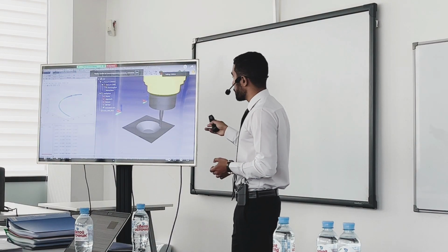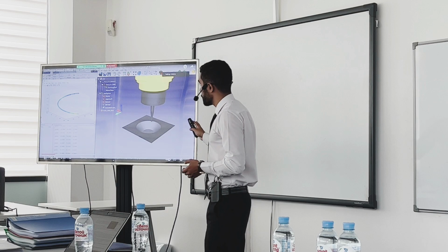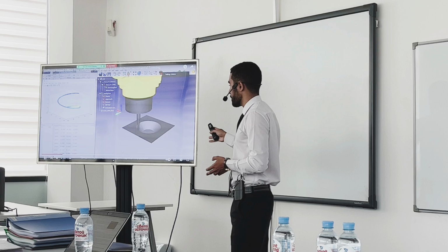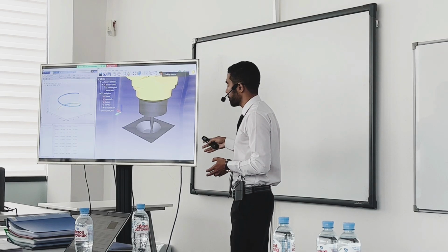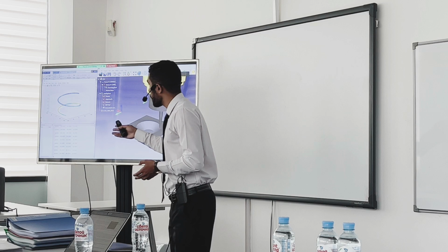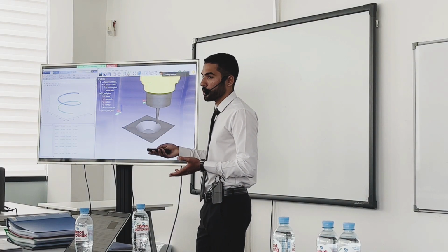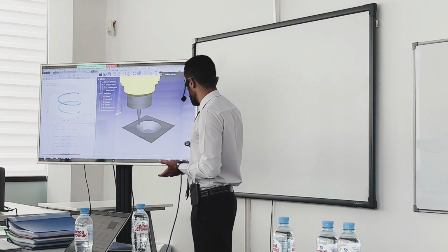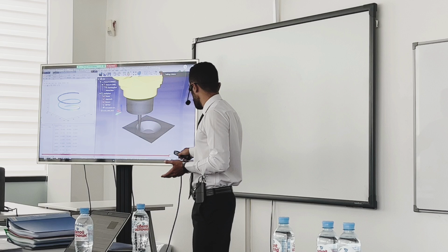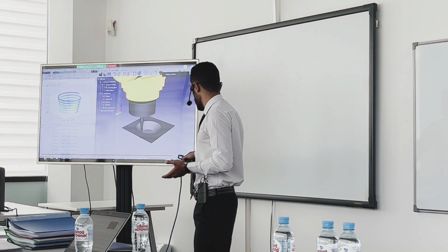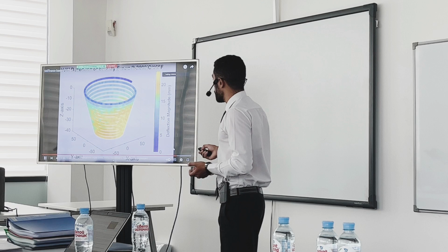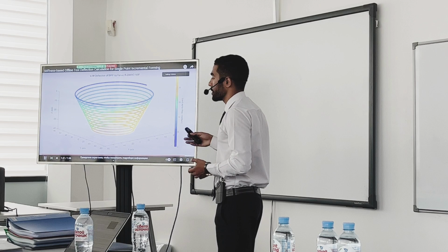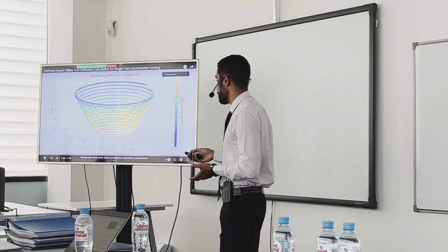Okay. So in this demo, I'm using RoboDK and MATLAB. On the right side, I'm solving the forward and inverse kinematics of the toolpath that I'm trying to generate. And on the left side, I'm applying the virtual joint modeling, and at the same time calculating the deflections. At the end of this toolpath, the model will generate these deflection maps that will be used later for the compensation.